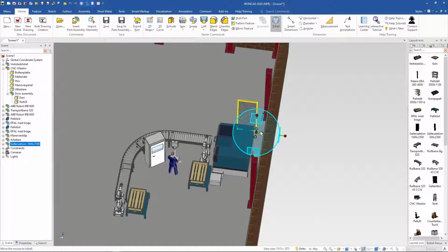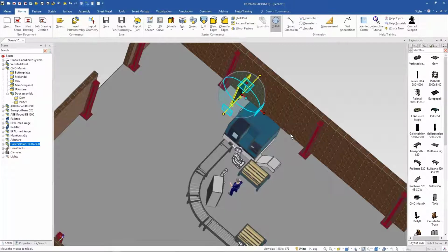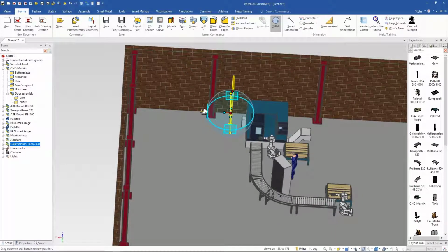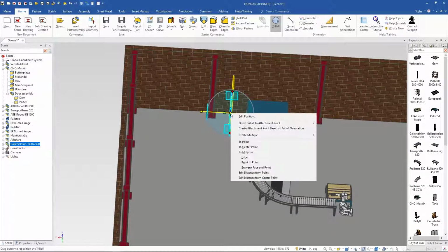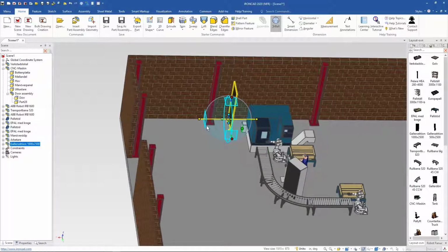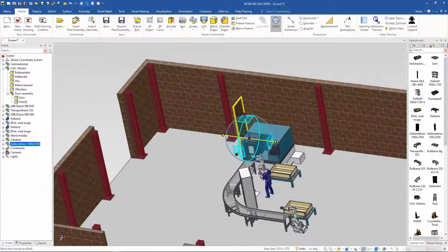And watch this. I know that this is the outside edge, so I can just do this. Say, you know what? Move this against the wall. So there's the first thing, and it has to be halfway between these two. Why not? I want to just pick up the point from this face here to the face of this, and that fence is now into position.